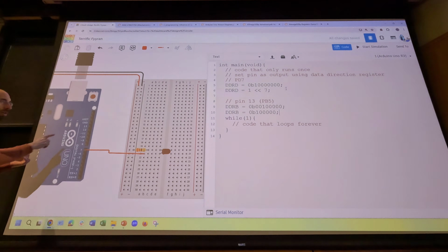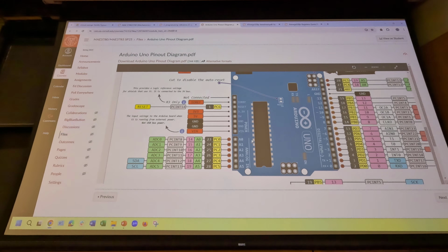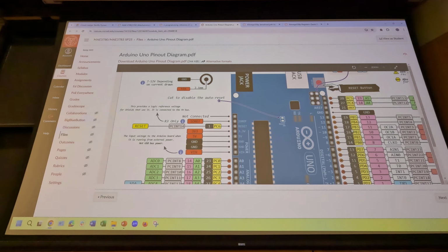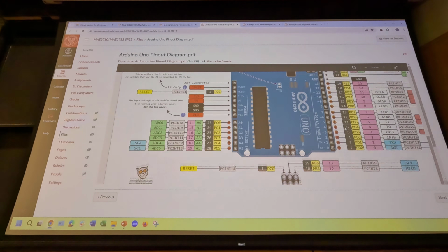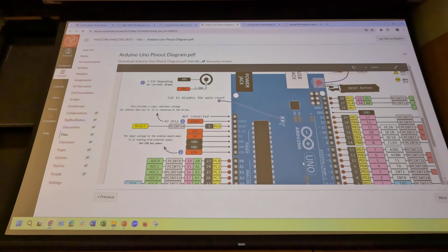Even if this part of the Arduino, again, it's kind of weird how the Arduino is laid out. On the text printed on the Arduino board, these 5 over here are labeled as analog inputs. You can still use them as digital pins. So they're part of port C here. And there's this header thing down here that has male jumper pins on it, and that actually has additional port B pins. So there are other pins distributed around the board that aren't necessarily right here. I think that might still only get you up to 7 port B pins. I forget if there's another one hiding somewhere. Does that make sense? Okay.